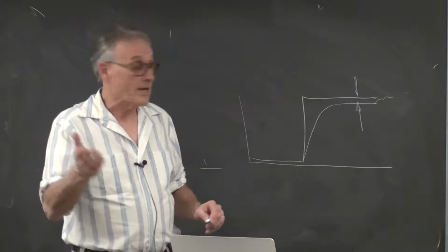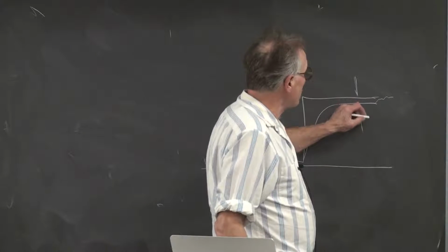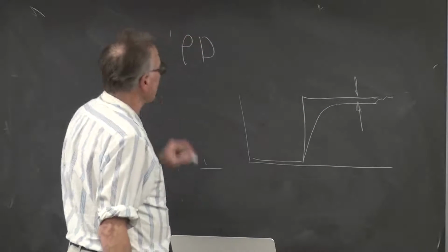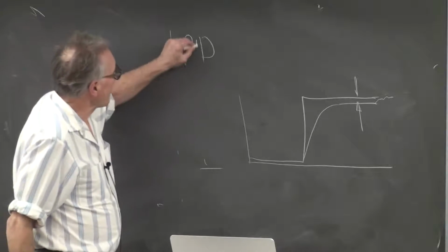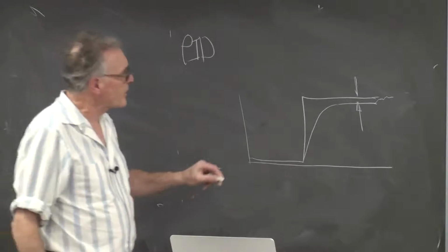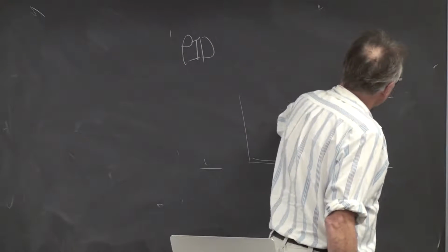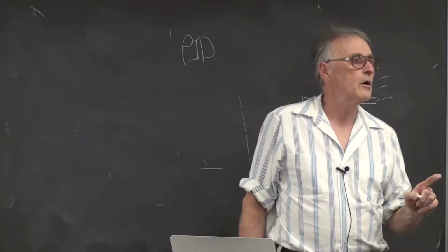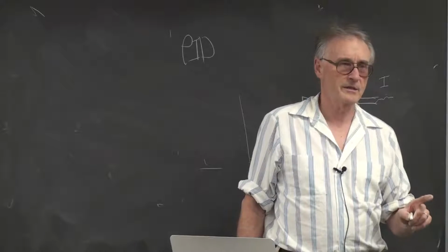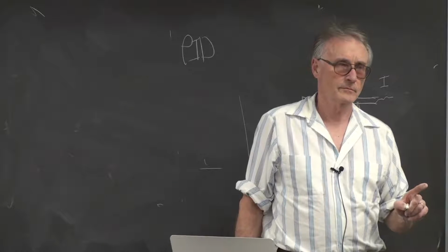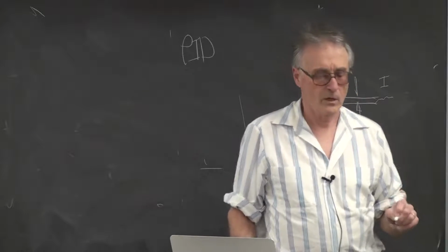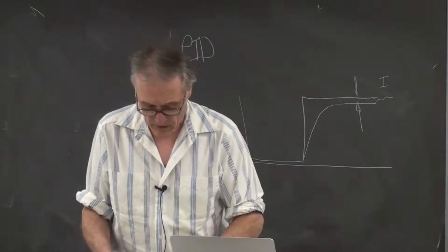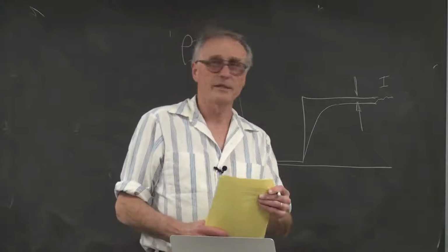Yeah, right, it's exactly. And what you could think here is that you could add another term. So we have a PD term. What if we were to add an I in the center and call it a PID controller and give it an integral term that says we're going to take the integral of the error over time and make that 0. So we're going to do a control which is proportional to the integral, but there's some horrible technical details here.